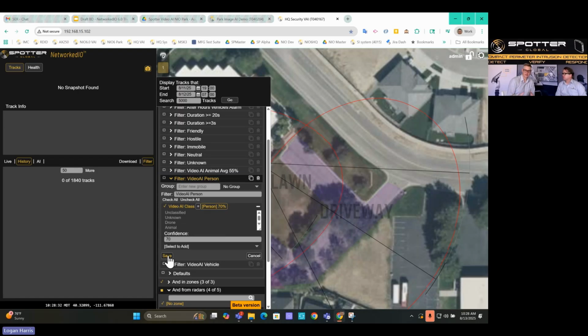So if you have an analog camera, you can go to an analog to digital converter, like an Axis encoder, which is quite popular, and turn it into a digital video stream. It does support both MJPEG as well as H.264 compression formats. So if your camera supports those, then we can bring the feed in and analyze it. If you have an old legacy camera system that you're currently using, you could put this on top of it with an encoder if required. But yes, if it brings in an RTSP feed stream that's encoded in MJPEG or H.264, it's ready to rock.